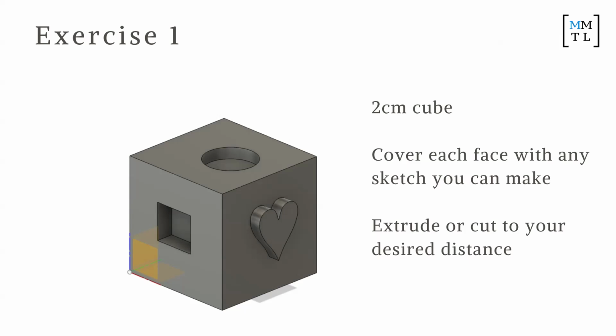How's the sketch going? Yeah, try it like negative, positive, see what happens. When you have two negative, see how that's positive too. Yeah, it'll extrude everything else as well. It's too much. If there's anything there, it'll extrude. So if it's over there, then try negative instead.